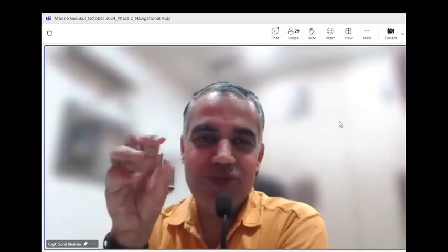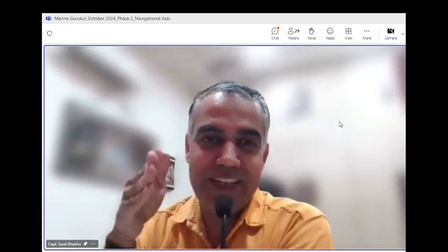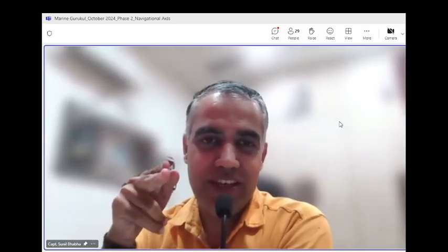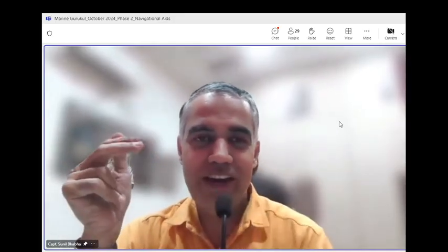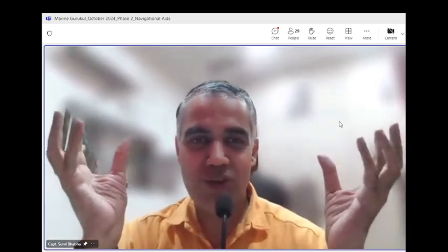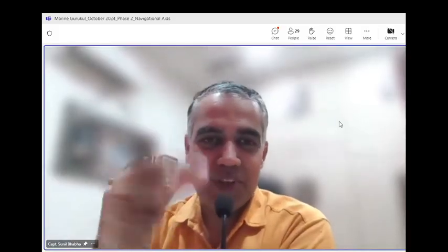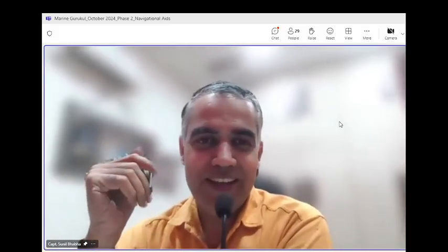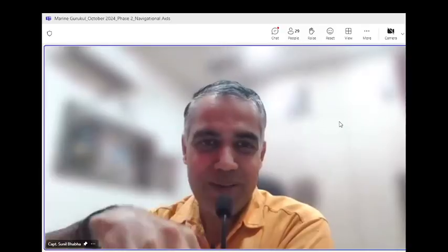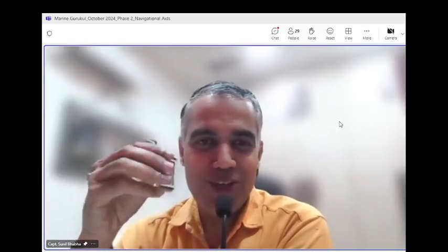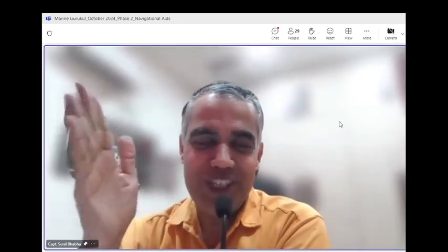There are different correctors which are fitted in the magnetic compass. You see, you may have magnets fitted in the fore and aft direction. There are some magnets which are fitted in the athwartship direction. Then you have the soft iron spheres on both the sides in the athwartship direction. You have a cylinder bar, which is forward of the pinnacle. And you have a heeling error bucket, which is exactly below the compass, fitted with a chain and pulley. So all these correctors are there, and they are correcting the different coefficients.